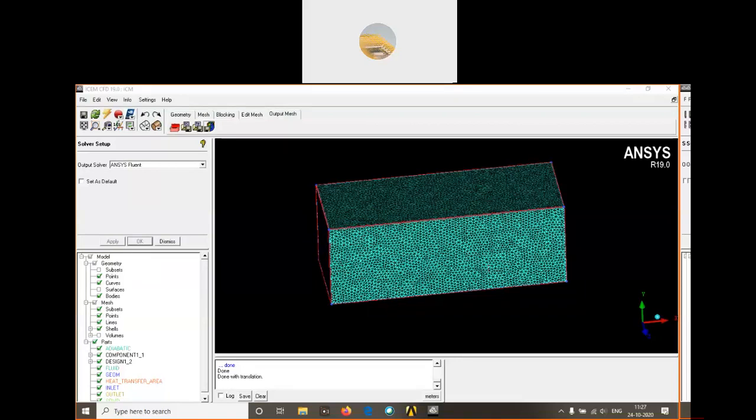I have created mesh of that much volume. In that case, the problem will solve for 2 days, 3 days, 4 days. After 4 days, if the solution is wrong, again I have to wait for 3 more days. So in such case, we will go for polyhedral mesh. It will bring down the mesh count by 50%. If the mesh is like 1 crore, it will bring it down by 50 lakhs. Just you can see the power of polyhedral meshing. Very good. So you can use it, but in this case, I'm not using that.